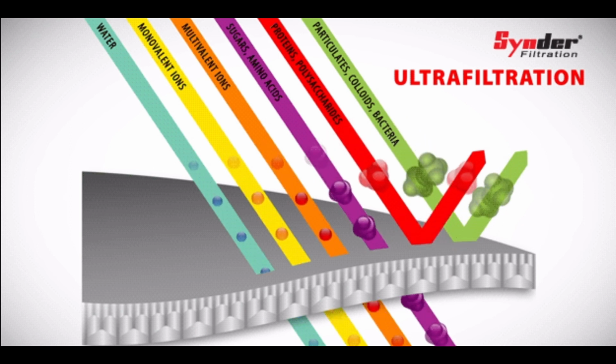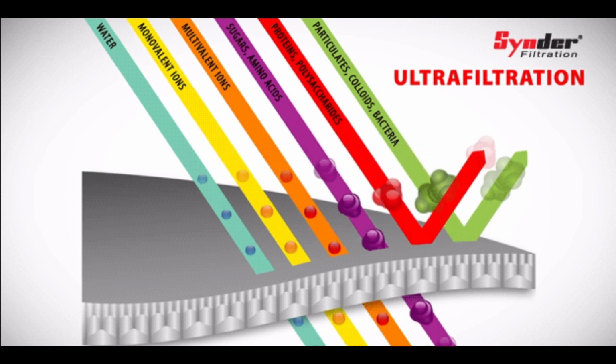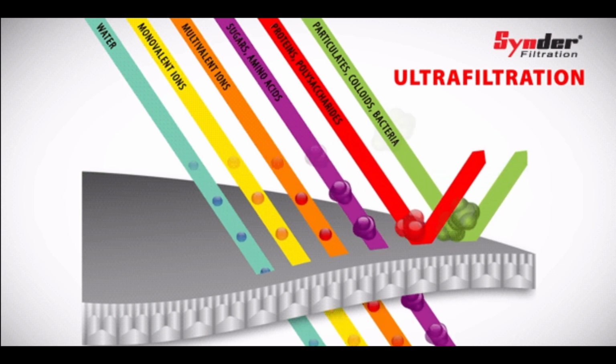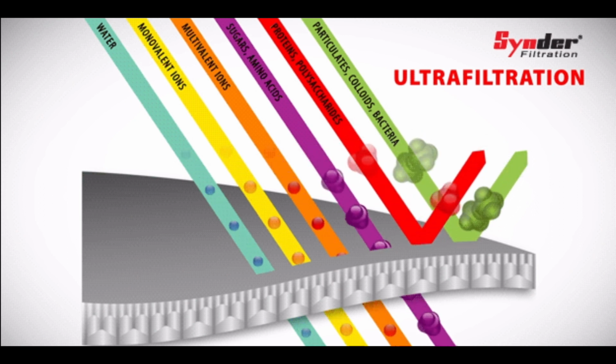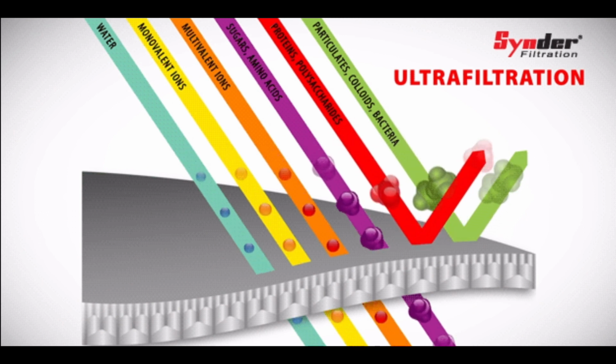An ultrafiltration filter has a pore size around 0.01 micron, while a microfiltration filter has a pore size around 0.1 micron. So, when water undergoes microfiltration, many microorganisms are removed, but viruses remain in the water. But under ultrafiltration, it removes these larger particles and may remove some viruses. Neither microfiltration nor ultrafiltration can remove dissolved substances unless they are first adsorbed with activated carbon or coagulated with alum or iron salts.